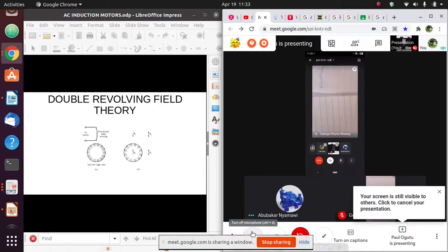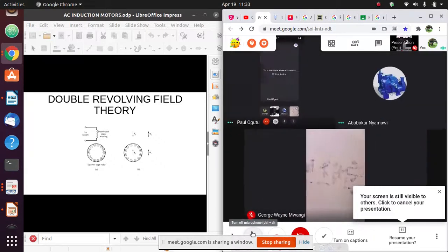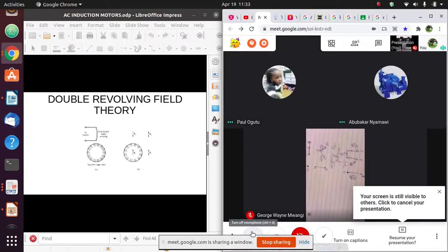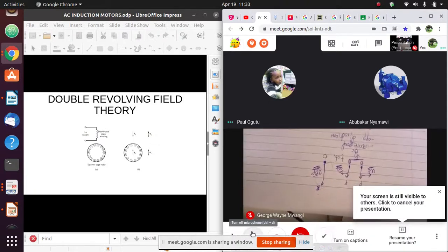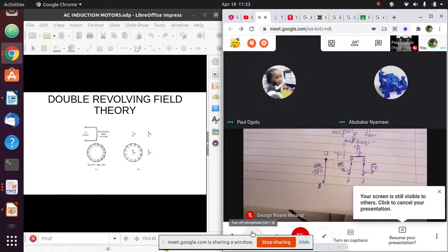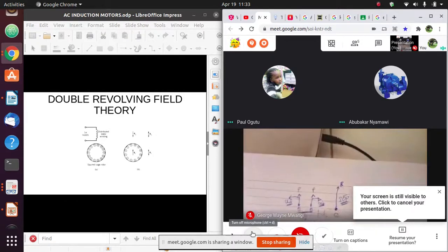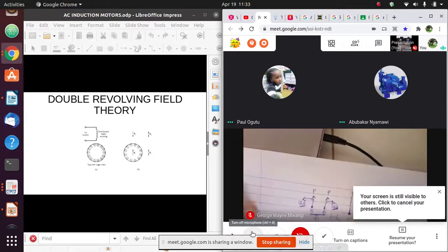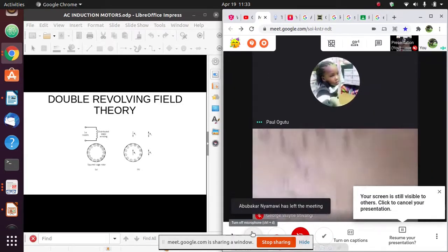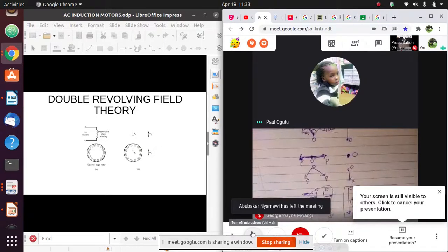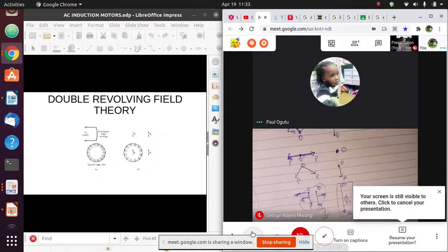I don't know if you can hear me now. Can you hear me? Yes. I was explaining how we resolve the rotating magnetic field, the pulsating flux produced by the stator, as two rotating magnetic fields that are rotating in the opposite direction.